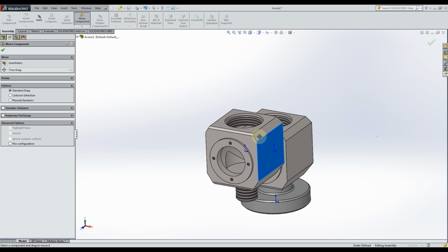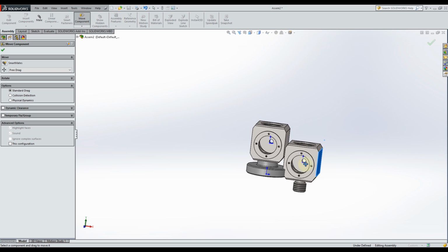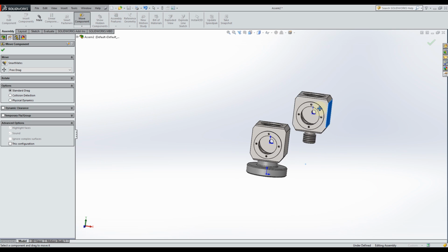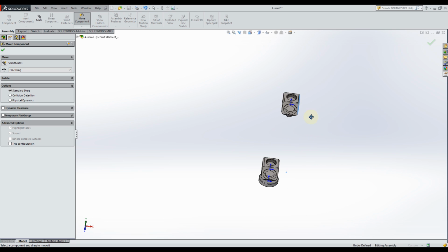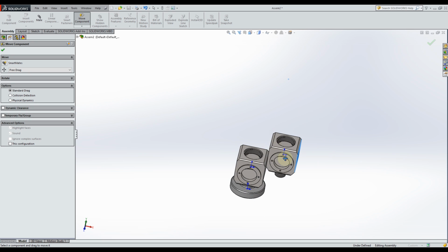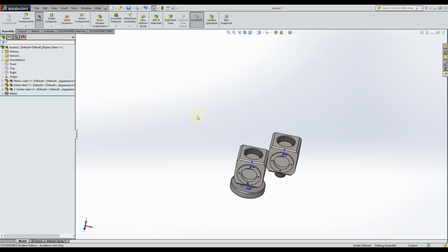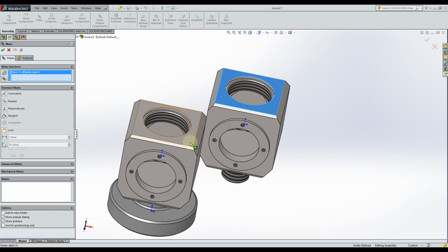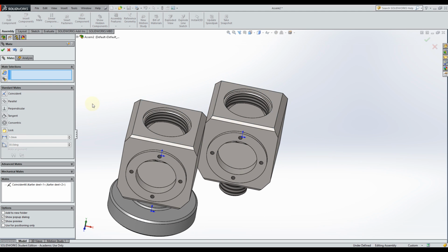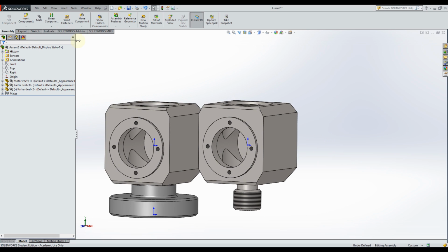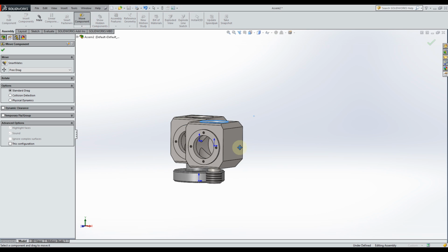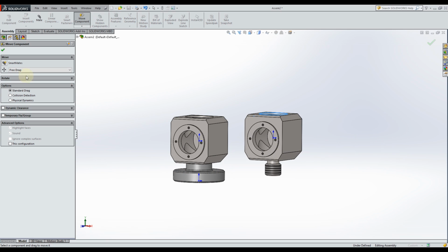Go to move. And I can then move the part, but the two faces will always remain coincident. It looks a little bit weird because you're always viewing it in 2D. But if you move it around, you can see that the parts will always remain attached together via that face. Now if I add 2 other mates, so if I select this face and this face, click on OK, then they are mated together. And now if I move the component, it can only move front to back.